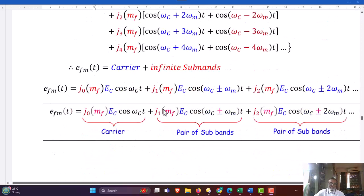The same thing is shown here. Only the coefficients J0, J1 and J2 are shown. So the first part is ωc. J1, the second term, is a pair of sidebands shown here. ωc + ωm is one sideband and ωc − ωm is another sideband. So ultimately, cos of (ωc ± ωm)t is a pair of sidebands. So there is generation of multiple pairs of sidebands.